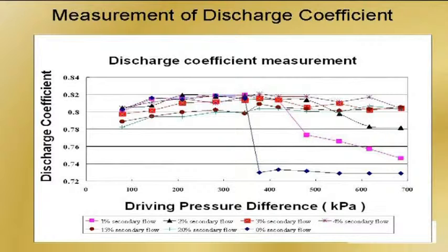We know from the imaging that it's controlling hydraulic flip. It's forcing the cavitation to stay within the orifice rather than extending all the way down and out the bottom to create hydraulic flip. And here, even with 2%, we get a huge change, and up to 3, 4, and higher percent, there doesn't seem to be any evidence of hydraulic flip, and our facility topped out at that number there. So these little changes inside the orifice are causing some big changes in behavior.